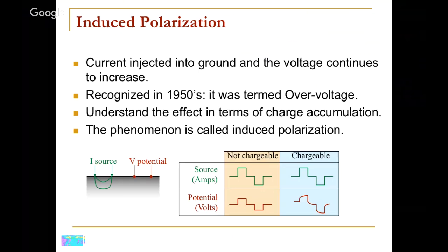We had a source. Remember, we just had a generator here, and then we could measure the electric potential any place else. So if we had just a current source that went up like this, so this is 0, this is positive, it's on, turn it off, dot, dot, dot. If we measure this potential, it's actually got the same kind of shape. When the current goes on, the voltage rises. When the current goes off, the voltage drops down. And so that was the information. We used this voltage as well as the geometry of the system to estimate what the apparent resistivity was for each measurement.